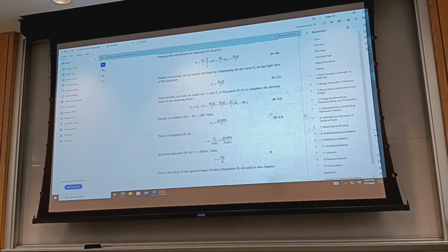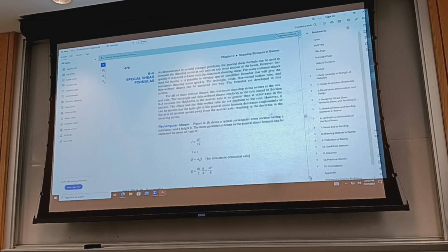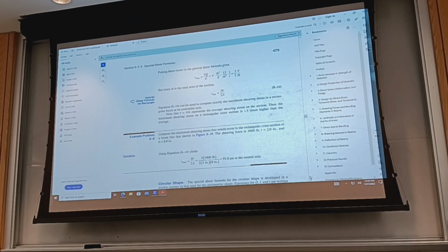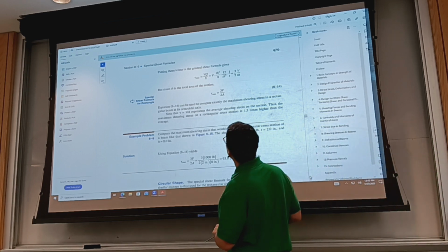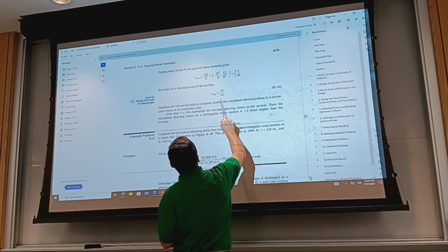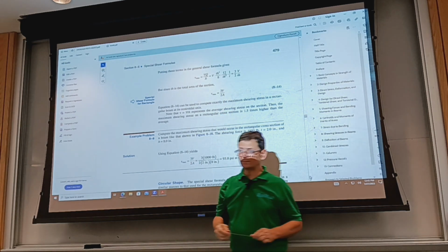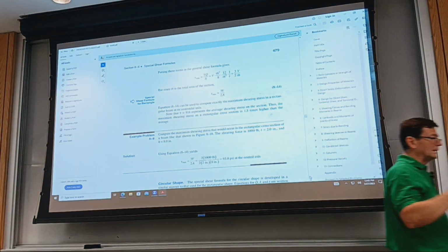If you're to calculate the maximum shear stress for certain sections, you can either go through the process of evaluating the first moment of area, or use some exact or approximate equation. So if you have a rectangle, the maximum shear stress will be 3/2 shear force over total area. Again, this is an exact formula.